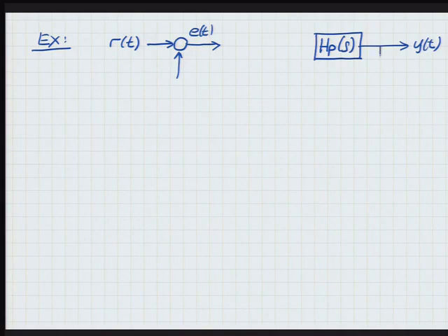So how do you do that? You take y, you compare it to the reference. That's where you want to be. That's the speed you want to be at, right? R of t is that. Y of t is where you are actually at. So there's a sensor in this feedback. And then you compare them, and you generate E. Now you know why I called it E. Why? Error. How far are we away from the reference?